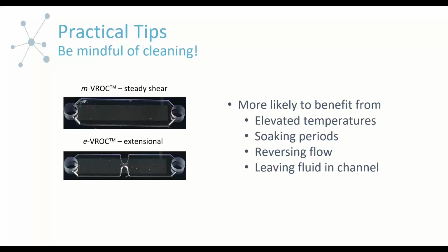So the first thing we want to talk about in terms of practicality is that cleaning is always very important in our microfluidics, but it's extra important when we're dealing with the extensional channel. I've brought the images back to drive that point home. It's always important in the uniform channel because of our small length scale dimensions, particularly the depth. But now we're introducing this significant constriction. So you can imagine that if you're not very careful in your cleaning, it can easily get clogged up. And then you can also have stagnation points that can be hard to clean.